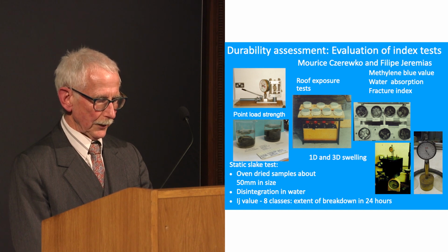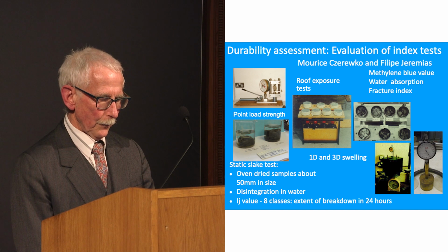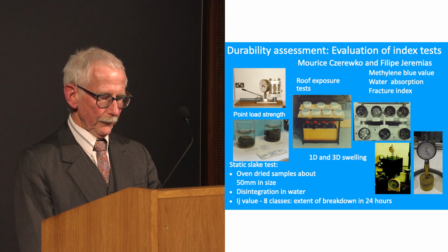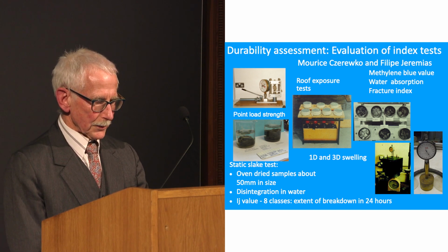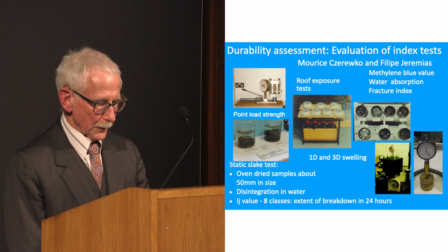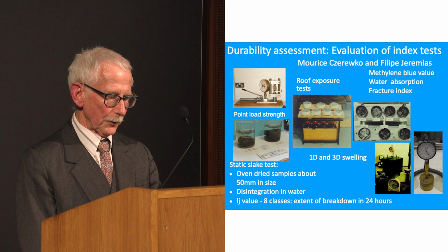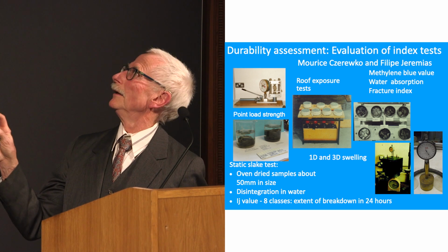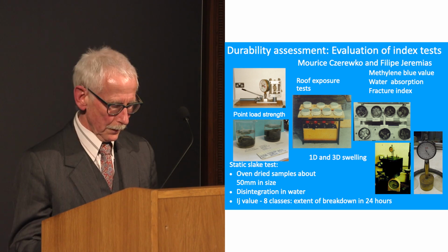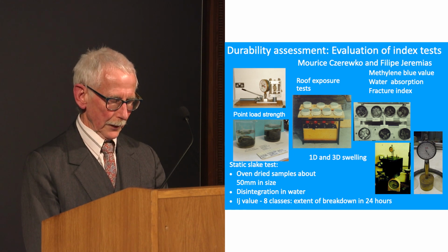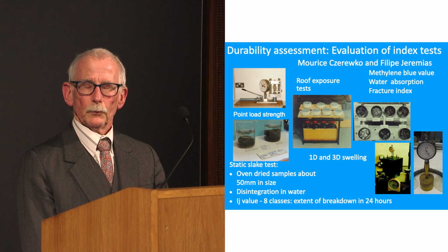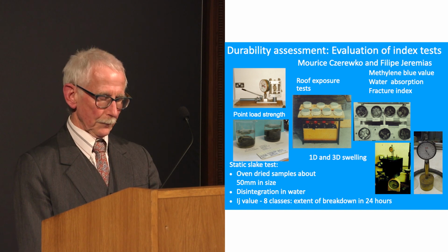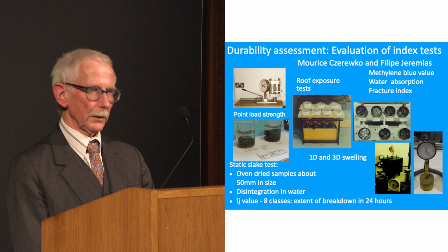Various index tests were evaluated, including static slaking, point load strength, porosity, water content, water absorption, methylene blue value, fracture index, and swelling. Static slaking consists of immersing dried pieces of rock in water and observing the breakdown that occurs in 24 hours, as illustrated here. And the methylene blue value: methylene blue is a dye which interacts with swelling clay minerals, and will indicate the presence and the amount of clay mineral in a mud rock.